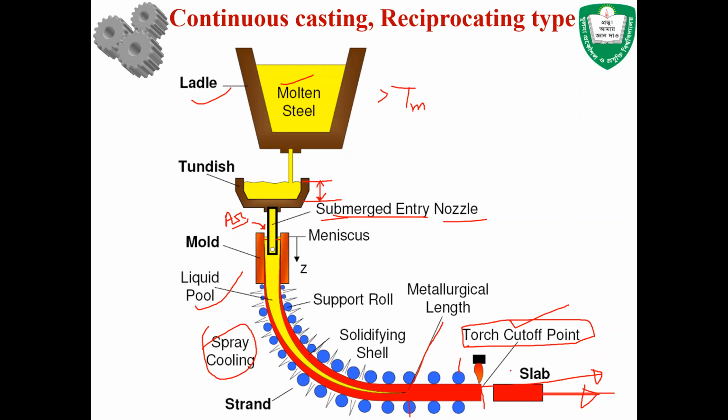It should not get out of the mold, because if the speed is slower and you put the molten material at a very high flow rate, then molten material will get out of the system. Okay, that will create hazards. So you have to really calibrate how much speed I should provide at the exit, so that I can maintain the flow rate using this height. The flow rate actually depends on the height of the material in the tundish or the secondary reservoir. That height determines what speed you should set up to take out the material from the system.